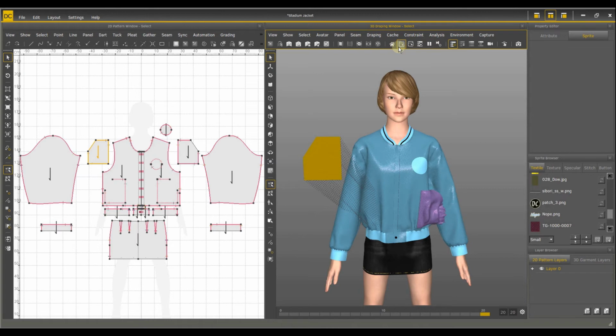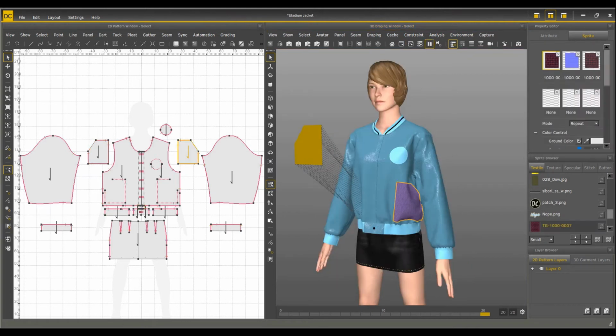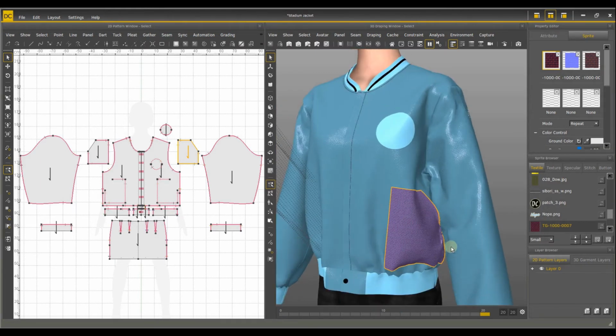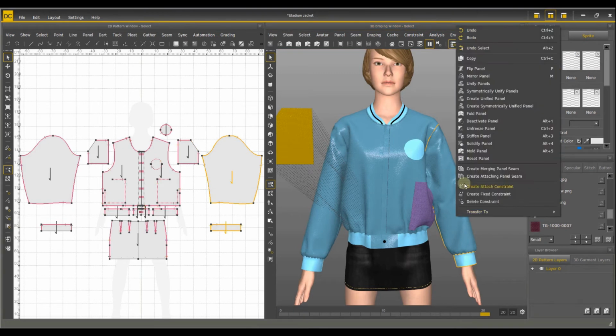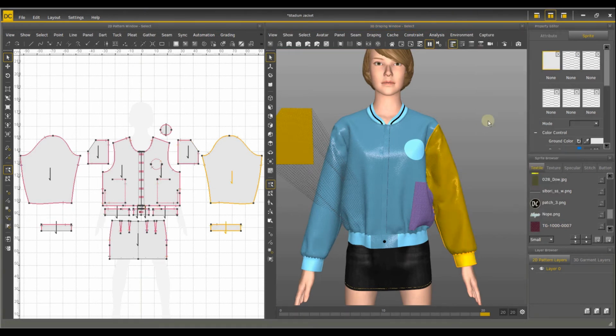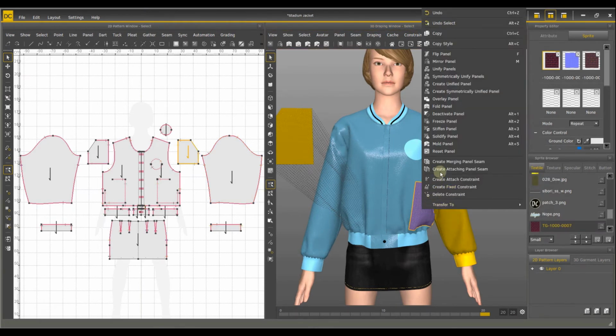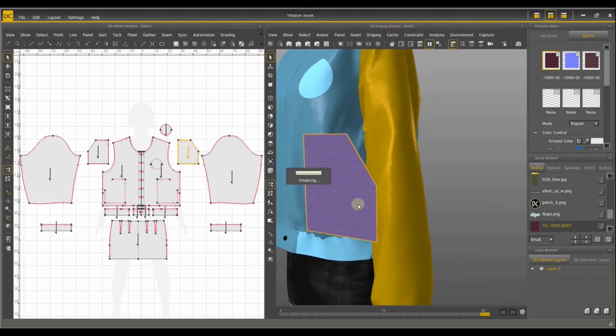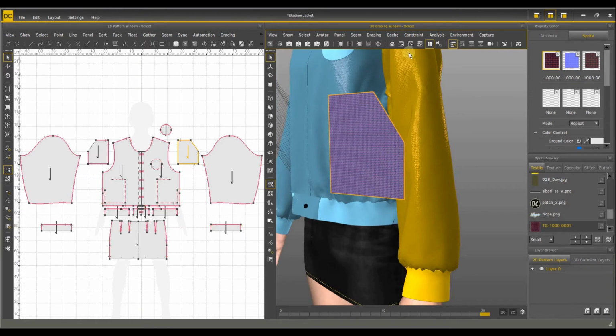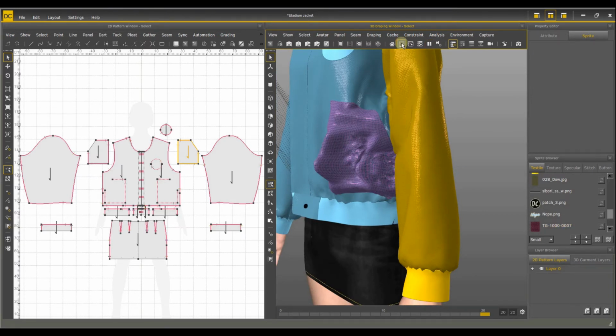You can find that the left Placket panel and the left sleeve panel will overlap during the simulation. To avoid damage caused by collision during the simulation, I want to change the status of the sleeve panel to Deactivate panel so that it doesn't exist in the 3D space and will not affect the simulation result of the Placket panel. After finishing the settings, press the static play button.